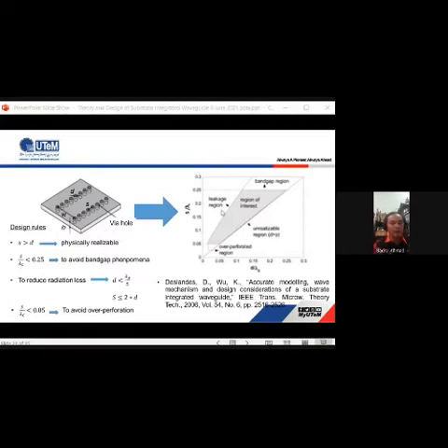If you put in more vias in the SIW, or substrate integrated waveguide, this is the disadvantage: the substrate will break. If you put a continuous wire of very closely spaced vias, it will break. And if you make the gap higher, the transmitted signal will leak through the gap. Okay, next.